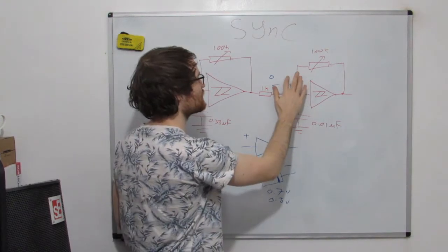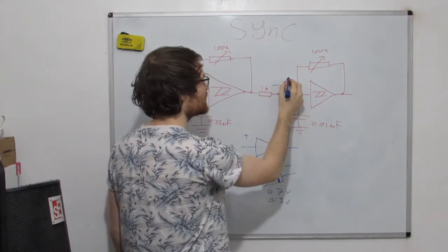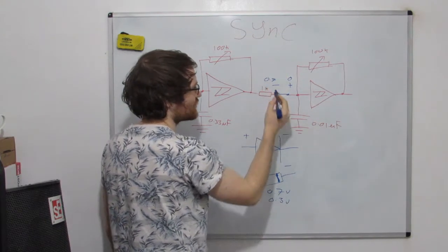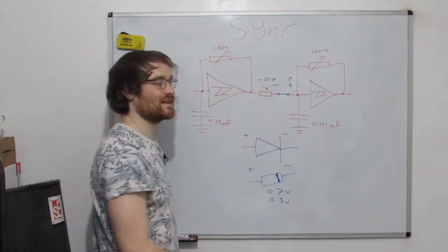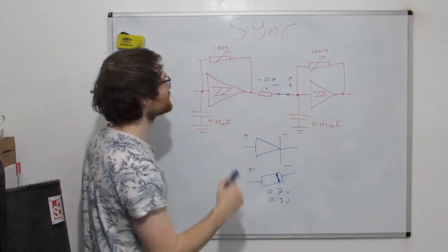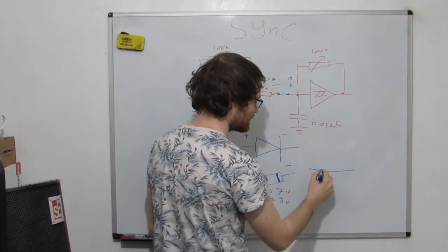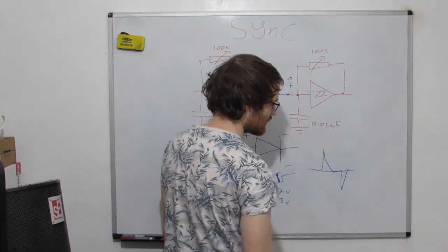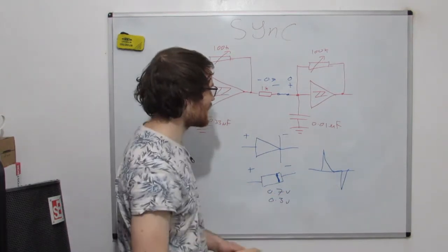But on top of that, you need to remember that the diode can also function if this is 0 and this goes negative 0.7 or more. If this was 0.1 or whatever, which can very easily happen by accident if you have capacitors discharging. Capacitors go like this when they charge and discharge. That'll be a charging cycle, and then when they discharge, they swing negative. So that can very easily ruin your circuit if you don't know. So be careful of these, and just be aware.